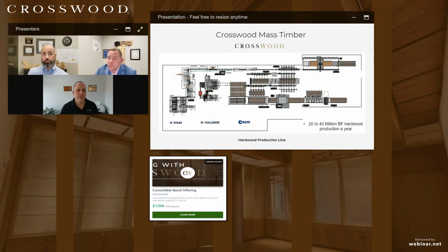And then, when we look at the different types of buildings that are being built with mass timber, the sweet spot is really those type 3 buildings that are 50,000 square feet and below. I would point to a bank, or maybe a small hotel. That's really the sweet spot where 60 to 70% of all mass timber builds.